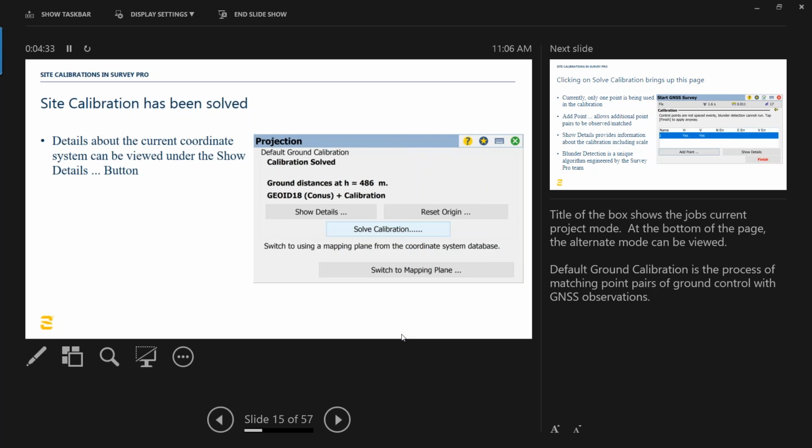Number one, your local elevation benchmarks and somebody else's definition of mean sea level might have a shift or a bias between them. And number two, actual gravity surface has a little bit of a tilt to it relative to the perfect geometric surface that GPS height is measured from. So you got two things to correct for. You got a shift and a tilt.